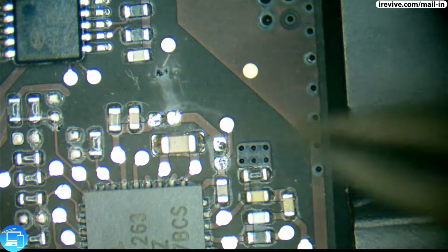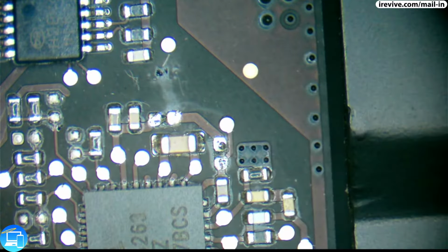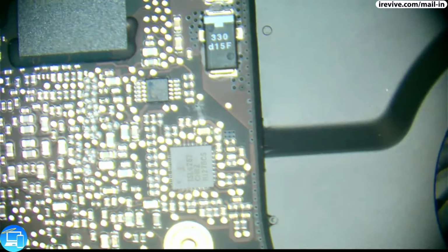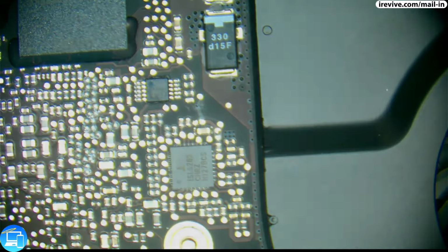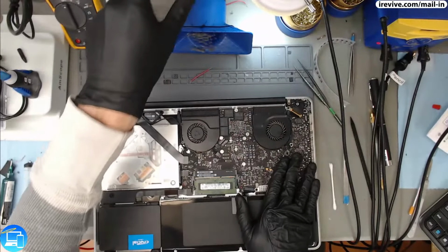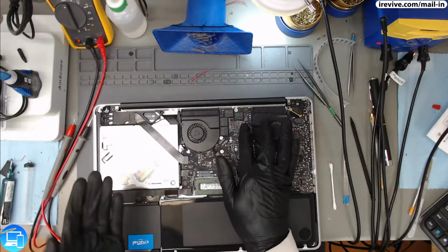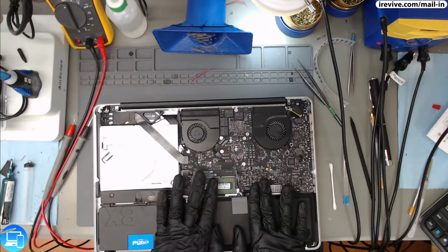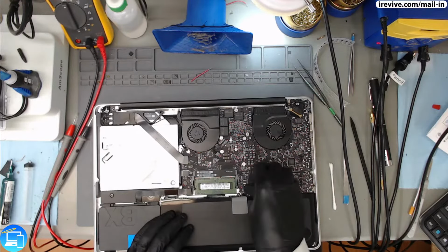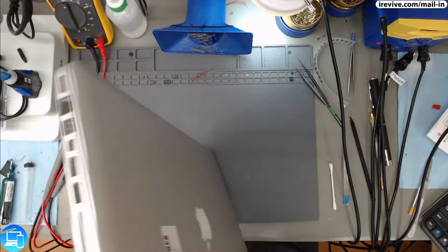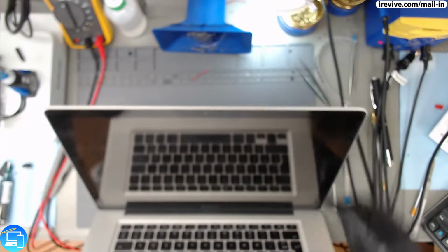And make sure that they're not bridged. Yep. All right, so R8911 and R8904 have been officially removed. So this graphics card has been successfully bypassed with the programmer and successfully removed with the voltage. Now, just to make sure it still turns on, let me plug it into our battery and boot back up.